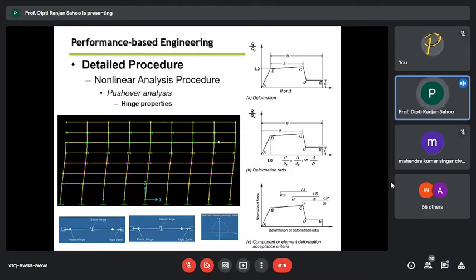So you have to understand that if a beam fails in flexure, how the flexural force deformation curve will look. For example, if you take a simply supported beam and in a lab apply 2-point loading or maybe single point loading, keep on increasing the loading till it collapses, and look at the curve, probably the force deformation curve or moment rotation curve.